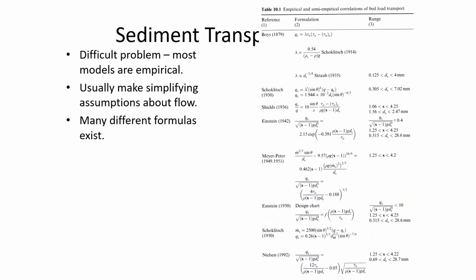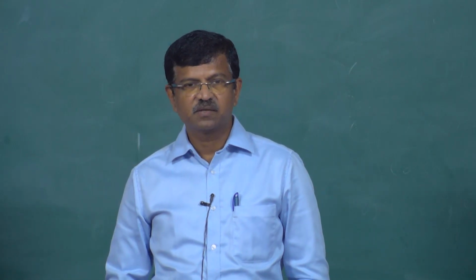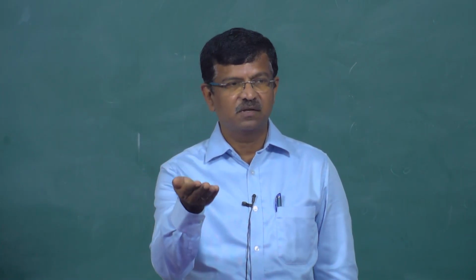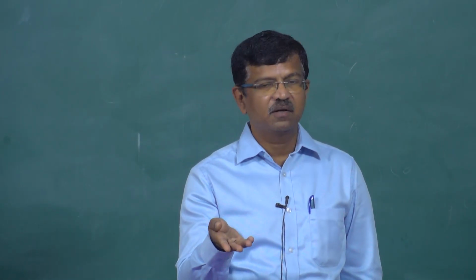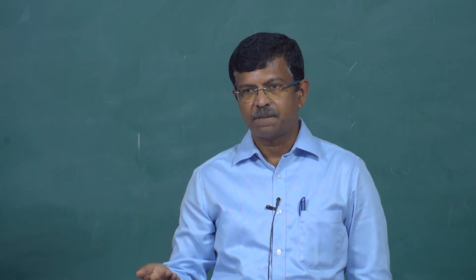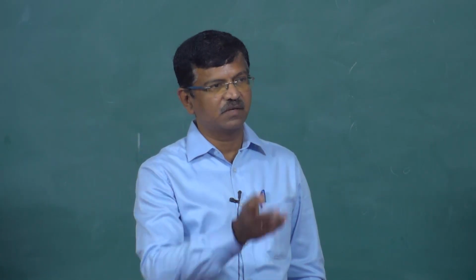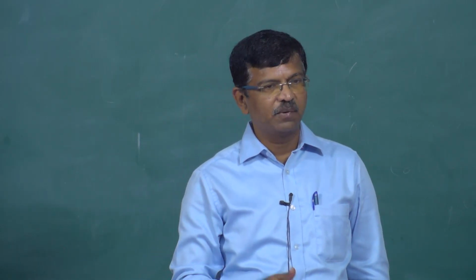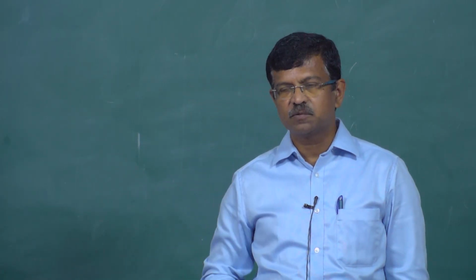There are so many empirical, or what some call semi-empirical, relations for the bed load transport compared to the suspended load transport. Bed load transport equations are much more numerous because of its complexity. The suspended load also has to cross the so-called sediment boundary layer and come out, but once it comes out it will just be affected by the flow. So, once it is in suspension it is easy to model compared to bed load. That is why many of the bed load transport models are very unique.